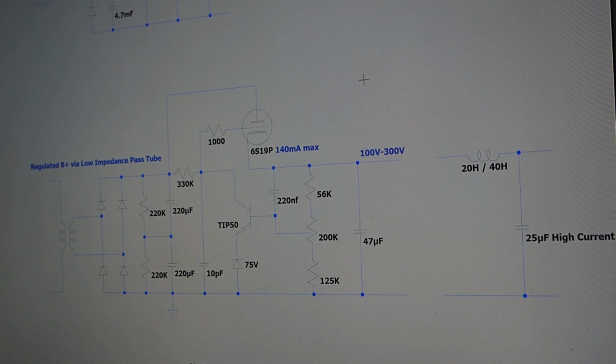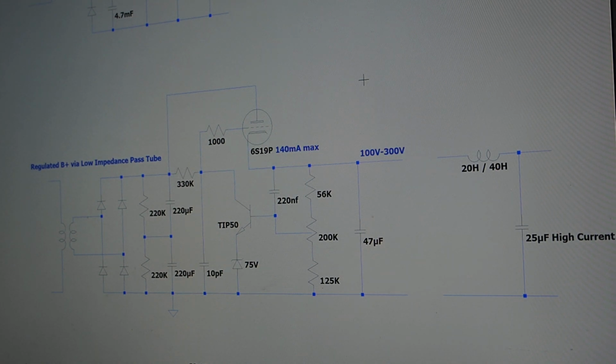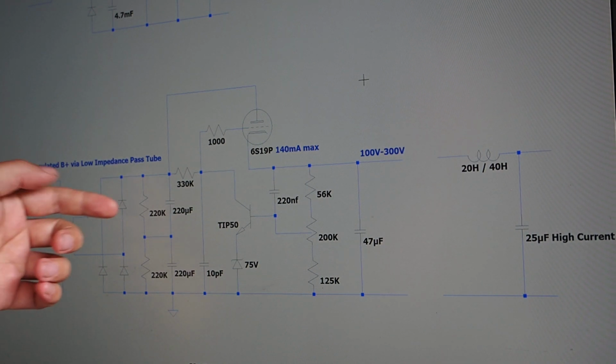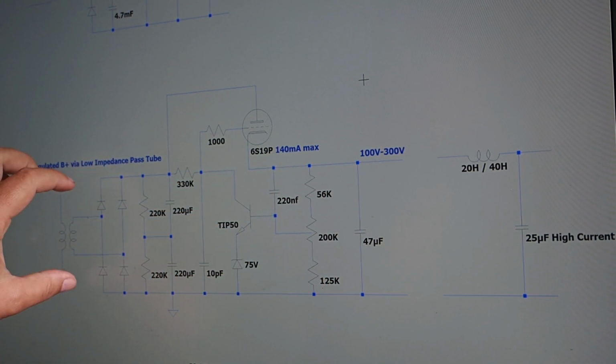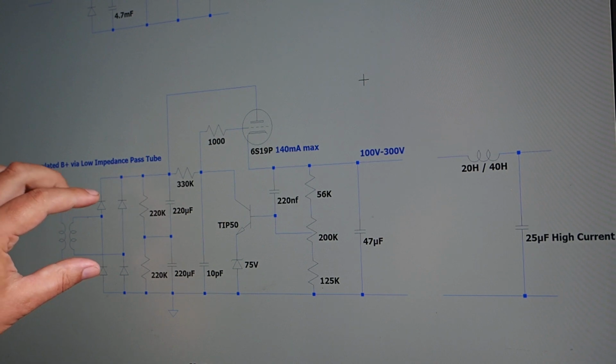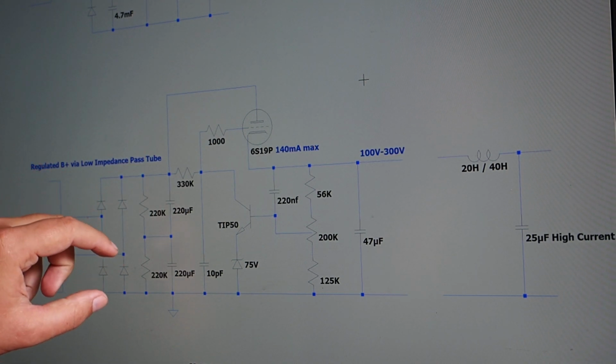So then finally, as the final part to this video, I hope now this starts to make sense to you. Some of the details, so let's just go into it. We've got our AC here, which gets converted to whatever is appropriate for your circuitry. It depends on the voltages you need, your choosing of the output transformer. We rectify it. I tend to use Schottky diodes here.